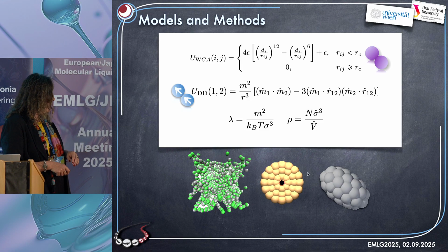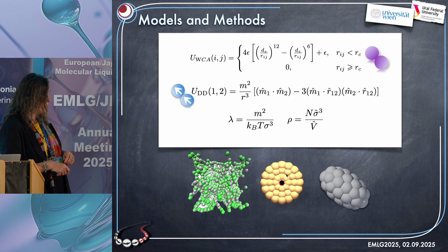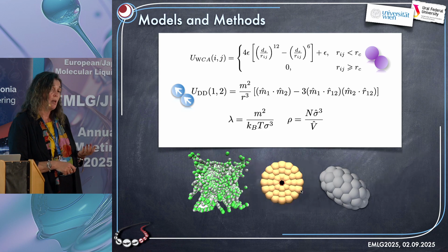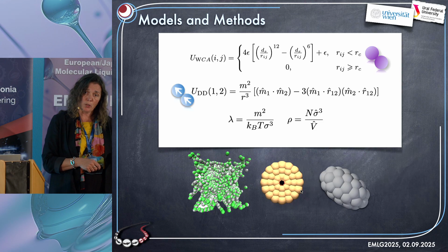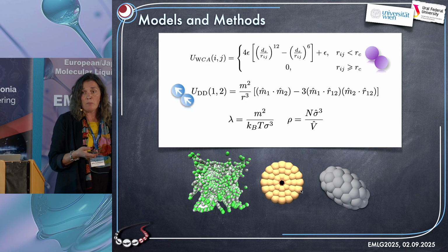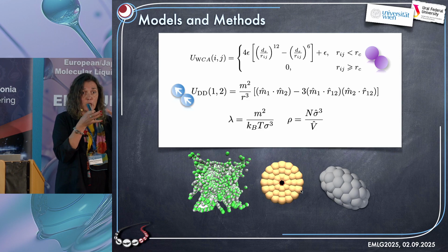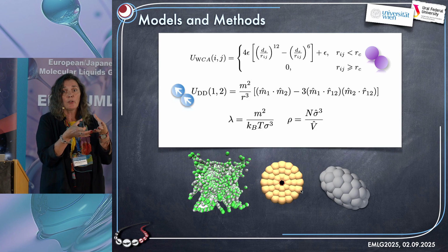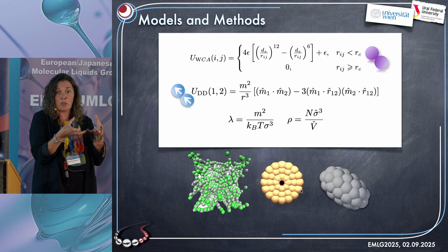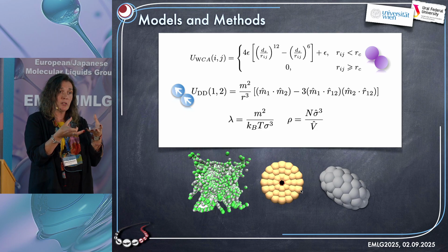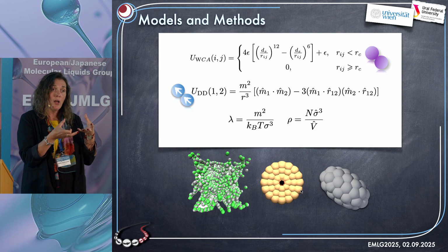So, but what if I want now, instead of a spherical particle, to have a particle that has an exotic shape, say an ellipsoid or a platelet? In this situation, technically you have two options. So first, you can model a shape as a closed potential if this shape is geometrically describable, like a superquadric, for instance, like a superball. That you can do.